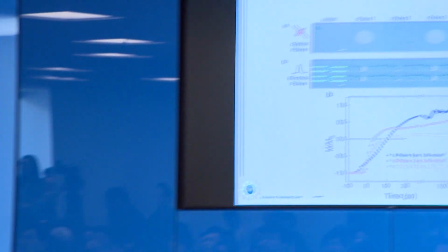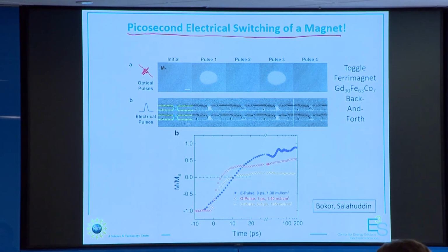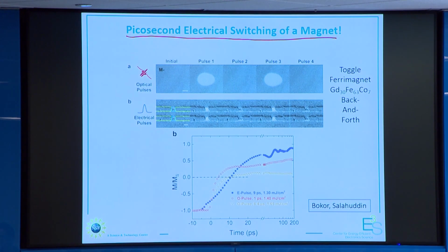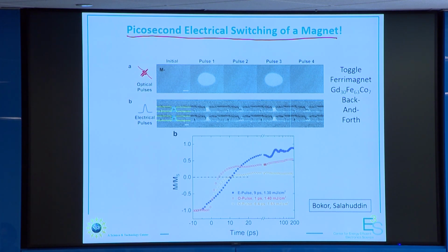And so this leads to a concept that is kind of interesting. First, I'll mention what my colleague, Professor Jeff Bokor, has discovered: that you can do a very rapid switching, because if you're going to do this, you need to switch the magnets very rapidly, and he found out that you could electrically switch a magnet. Now, normally it would be limited by the precession frequency, which is about 10 gigabits, and you can go down to terabit speed.